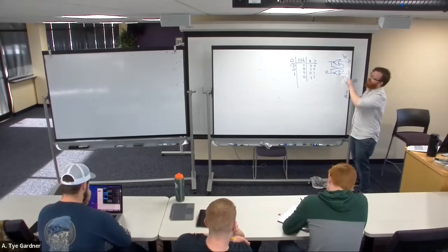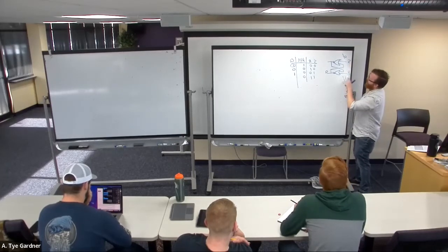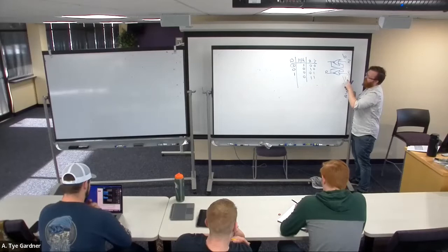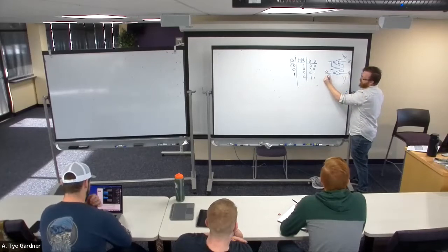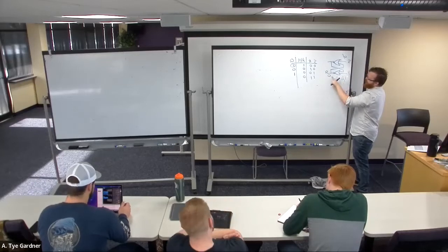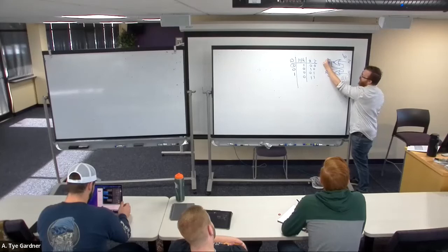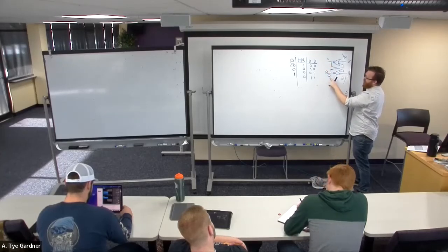Spoilers: set, reset, SR. That's the reason I chose those. So now set was 0, reset was 1, which meant that Q was 0. Well, if I transition from 0, initially the 0 got passed around. 0, 0 meant this was 1. A 1 gets passed around, which means the output is 0. It stayed 0.